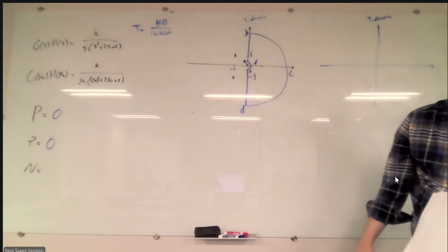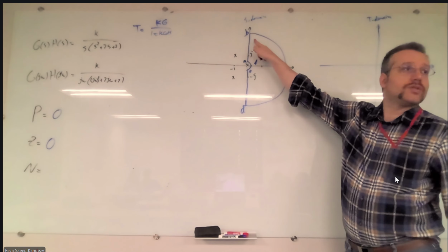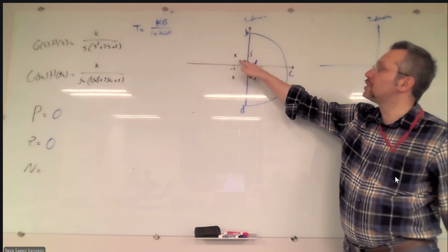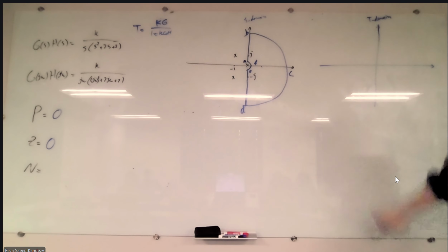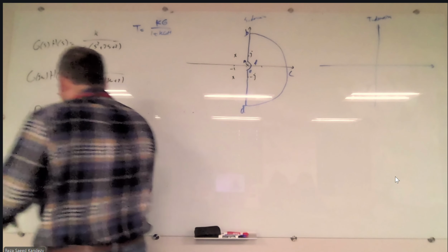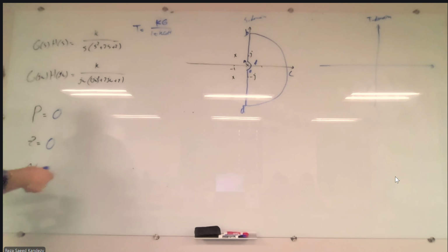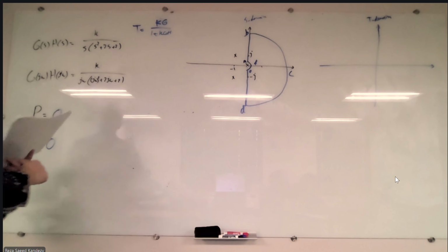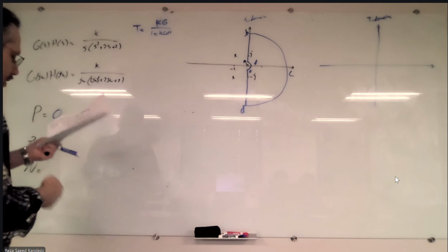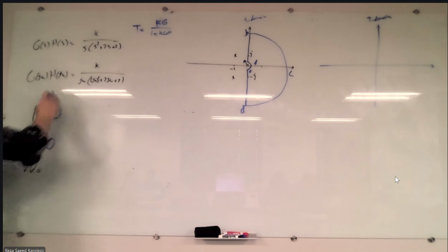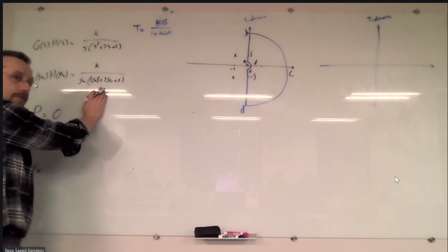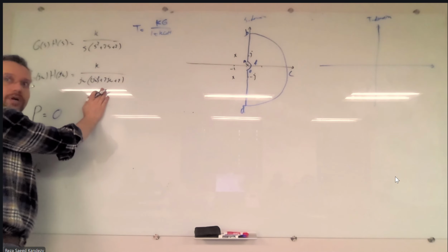Now I'm going to start mapping. For the mapping, we said we are going to use those specific points to find where these specific points A, B, C, D, E, F would fall in our mapped domain. So, for the first one, we need to calculate the magnitude and phase of A prime, which is the mapped point of A. In order to do that, we need the functions for magnitude and phase of our actual j omega transfer function.